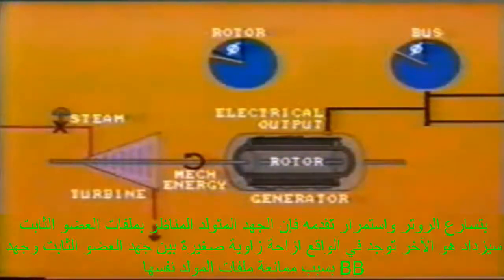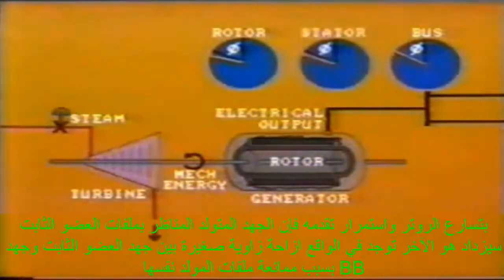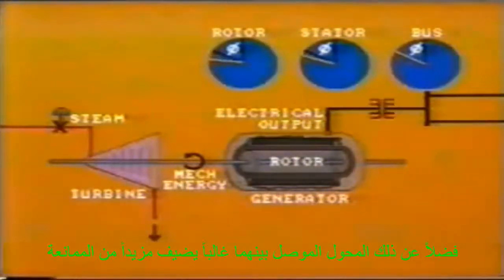As the rotor accelerates and moves ahead, so does the corresponding voltage, which is generated in the stator windings. There is actually a small angular displacement between this voltage and that of the bus due to the reactance of the generator windings themselves. Moreover, a transformer is often connected between the two, so adding more reactance.